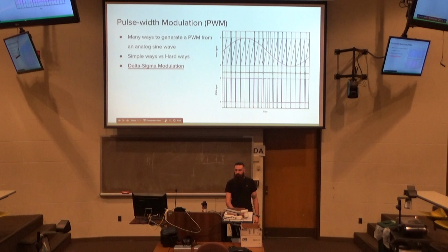You see how the blue wave is placed on top of the red. Now every place that your blue wave is lower than the red wave, you turn on your pulse width modulation. You can see between this point and this point here, the pulse width is on, and there are even nice lines to show you, because the blue wave is under the red wave.